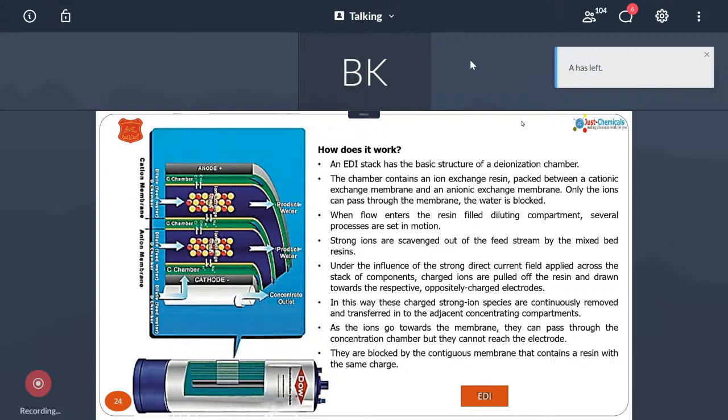So it involved a lot of acid handling, caustic handling, a lot of unsafe acts, and it was not continuous and needed to be monitored all the time for sodium, silica, and other things, and even the conductivity, which was required at 0.1 for high pressure boilers and power plants.